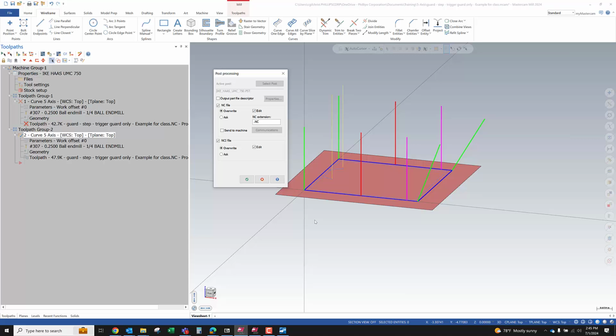Now, fortunately, we're dealing mainly with Haas machines, at least for the foreseeable future, based on the way that Federal operates as a division, which is great. Other machines have different technology and different complexities when it comes to producing 5-axis G code and what you can actually achieve. So there are some limitations to, for example, tool center point control and dynamic work offset.